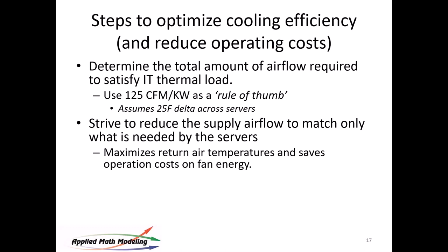But we know from the equation for convective heat transfer that if we're going to dump a certain amount of heat at a given altitude, then we're going to need at least this much air. It may be that you need a little more because the servers may be pushing more than they really need, but we need at least this much. So it serves as a good baseline for us to move forward.